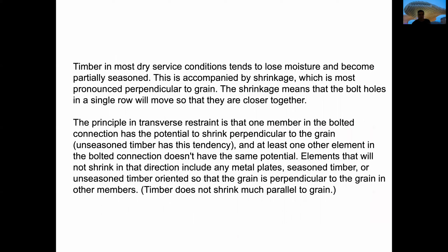Well, timber in a dry service condition usually tends to lose moisture, and it becomes something that is called seasoned. And this will have some shrinkage, and in most cases it will be pronounced when it's perpendicular to the grain. This is a problem because it means that the bolt holes in a single row will move when the element becomes smaller, because when losing water the dimension will become smaller.